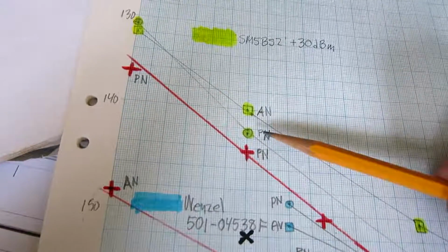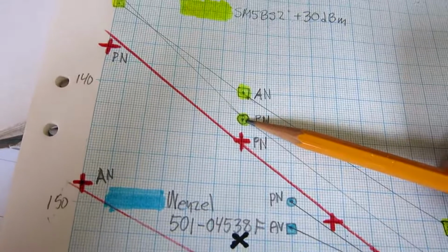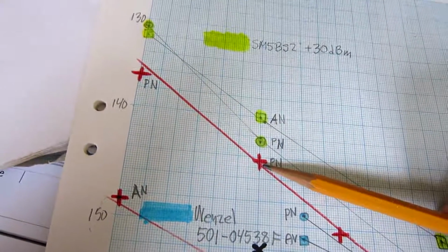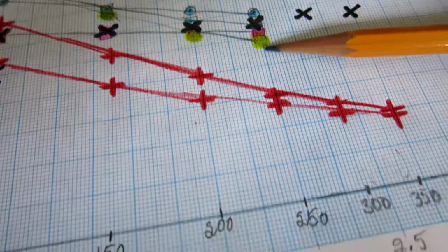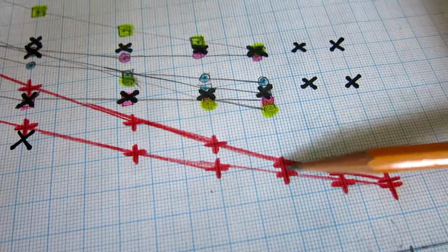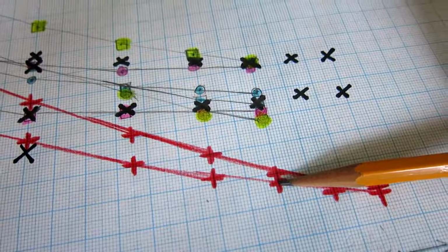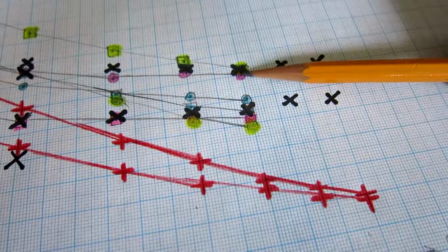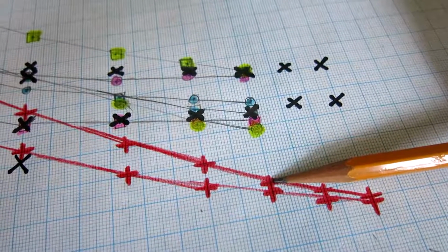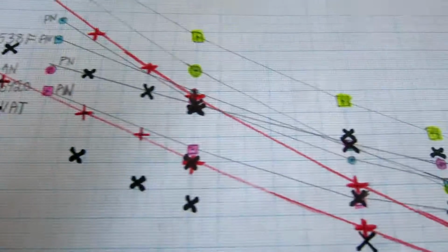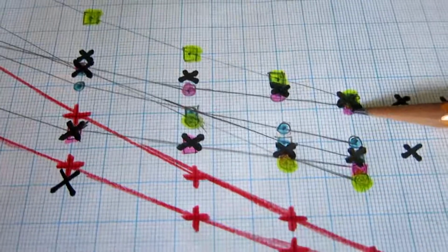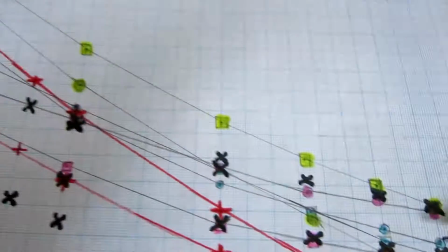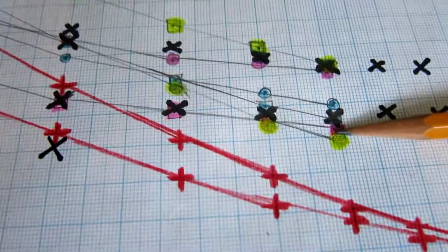The phase noise, the round dots, is also improved, but not so much at close range. A little bit more at a wide range, well, 250 hertz here. It goes down to this point. And at this range, the amplitude noise is improved from here to here. The measurements of the Wenzel are the red points, circles for the phase noise, and rectangles for the amplitude noise.